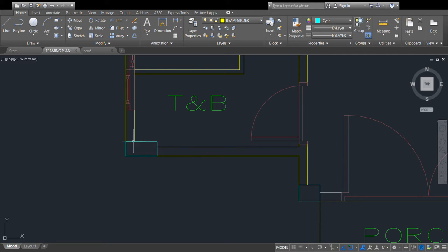Guys, notice. So this is the line, but it is flushed on the column. Now, avoid this portion because it will give you trouble with your printout. Remember, your purpose is to have a black output. Unfortunately, the colors tell you meaning. I chose cyan for column because it requires a thick line weight. The normal line weight is intended for walls and beams and even girders. The lighter weight is for windows and doors.